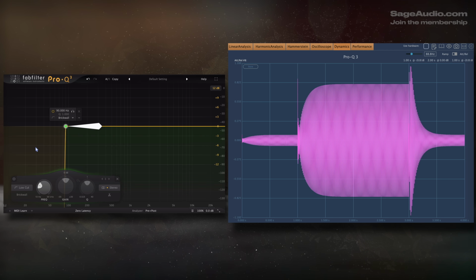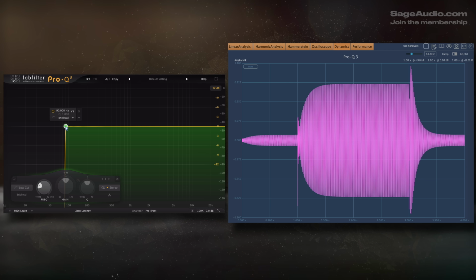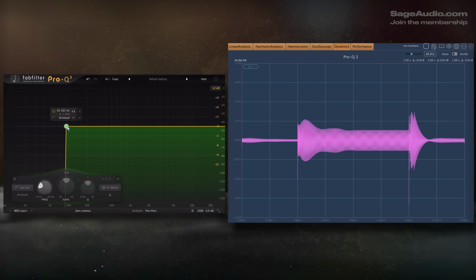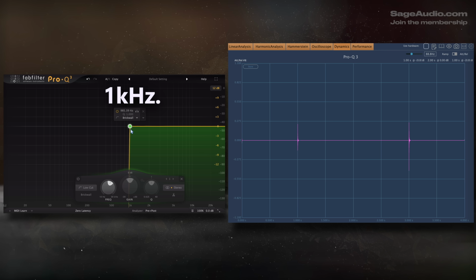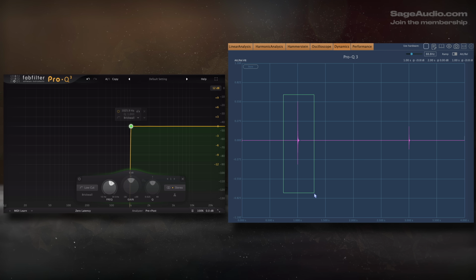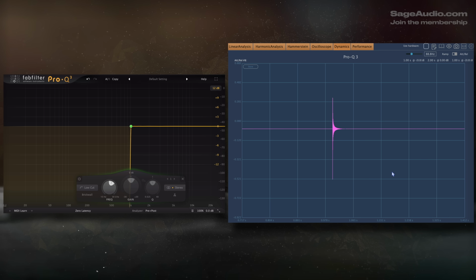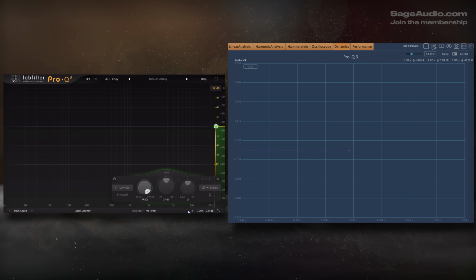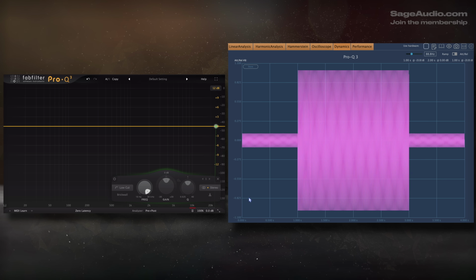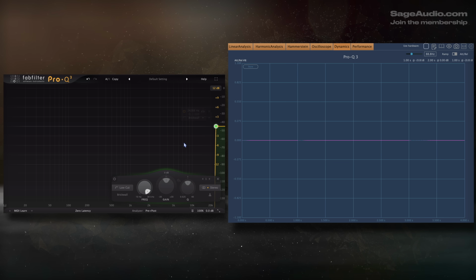Now what do you think will happen if I move the high-pass filter way past the sine wave's frequency? If you think that it shouldn't have a signal, or you shouldn't be able to see one, I thought the same exact thing, because that makes sense. But when the cutoff is at 1 kHz, 88 Hz is still present and it's modulating whenever the signal's amplitude would have transitioned from quiet to loud. It is not until the cutoff approaches 23 kHz that we finally fully attenuated the signal. Now, if I had asked you, hey, how do I get rid of a signal around 90 Hz? I can't imagine that your answer, or anybody's answer, would have been to set a high-pass filter around 23 kHz.